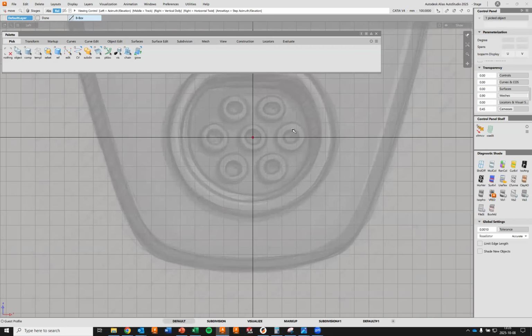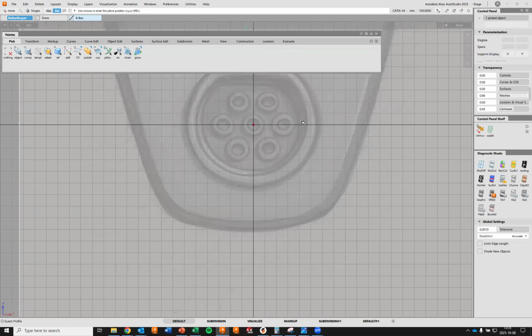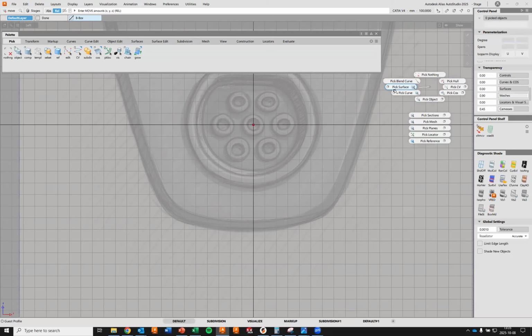Okay. Now I know for a fact that the diameter of this connector is 100 millimeters. So I'm going to draw a horizontal line here. I think I have some trash left there. So I'm going to draw a line using curves, use V curve, snap it to the origo using Alt, and then my middle mouse button to extend it slightly like that.